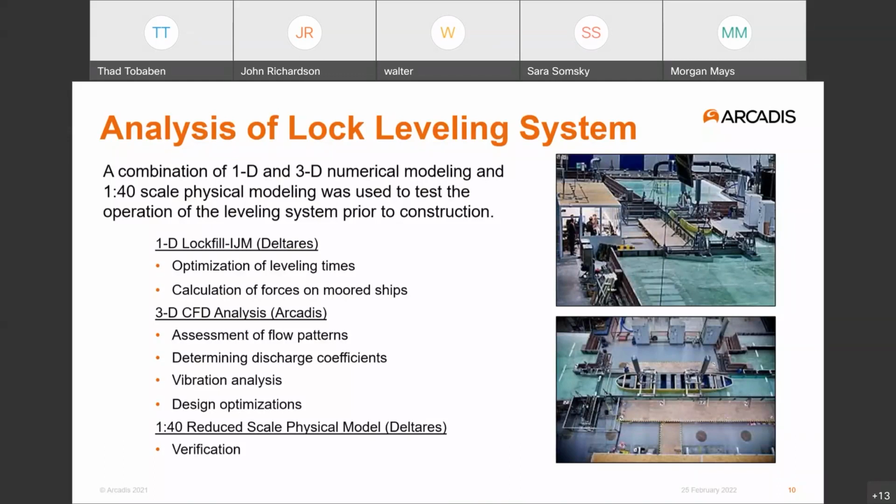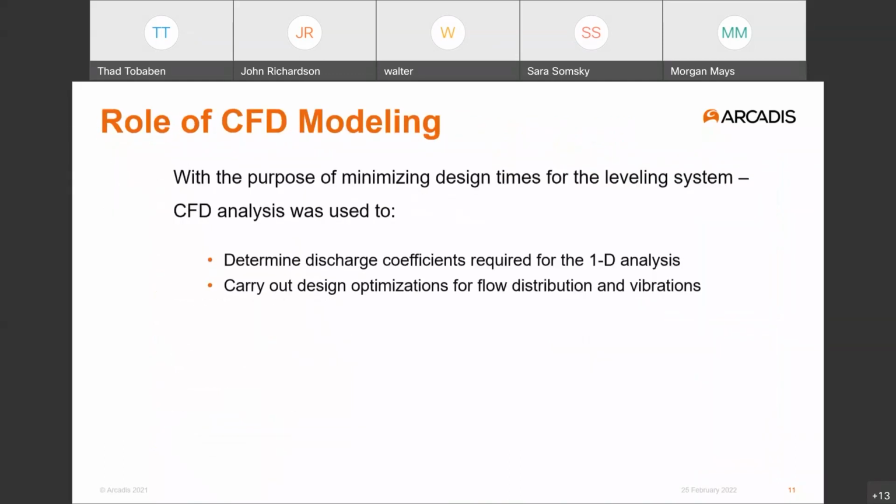So to summarize the role of the CFD modeling here: first and foremost, to determine these discharge coefficients so that we could design the leveling system and determine how it should be operated, and then also to carry out some optimizations to improve the design prior to construction.